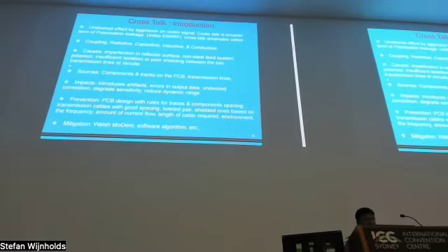The main sources are components and tracks on the PCBs and transmission lines as far as the receiver and digital backend systems are concerned, and even connectors. The impacts of this crosstalk are that it introduces artifacts, errors in the output data, undesired correlation, degrades the sensitivity, and reduces the dynamic range. Prevention.